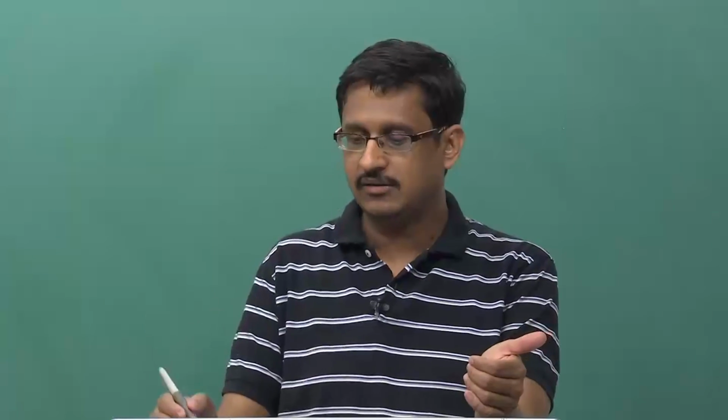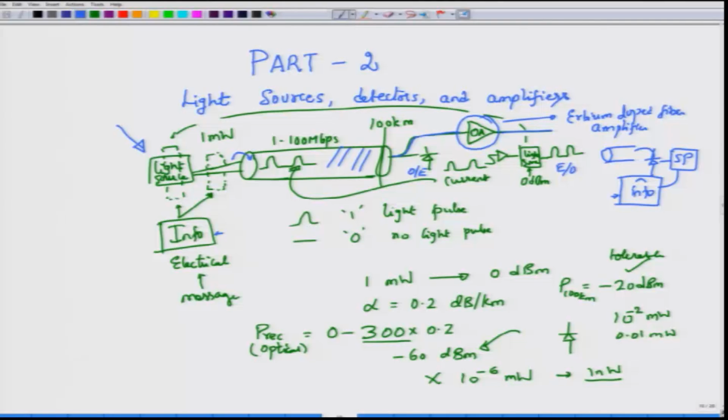If I were to perform an analog communication, that is, if my light would not be modulated digitally, but in an analog modulation format, then the signal that you would get would be a distorted version of the information that you have transmitted. So, for example, if you have launched this pulse, then the pulse that you would get would look something like this despite all of your effort, and whether this information is okay compared to this one is a decision that one has to make depending on the application.